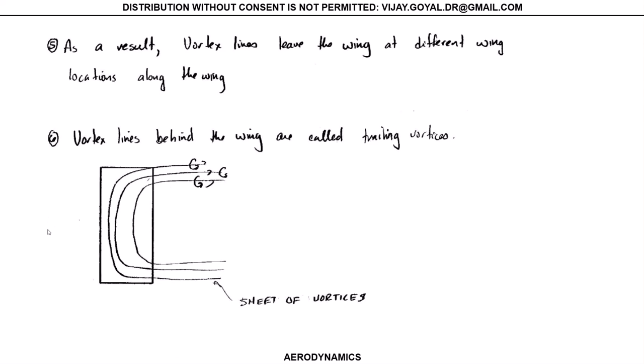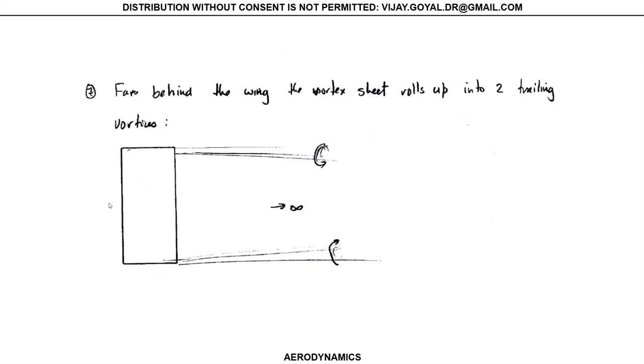So as a result of this, these are vortex sheets, and each one of the vortex sheets can have its own circulation. So call these gamma 1, gamma 2, and gamma 3, and that's going to be different. That's going to have a consequence on the value of the circulation across these lines. And we're going to look at that for a moment.